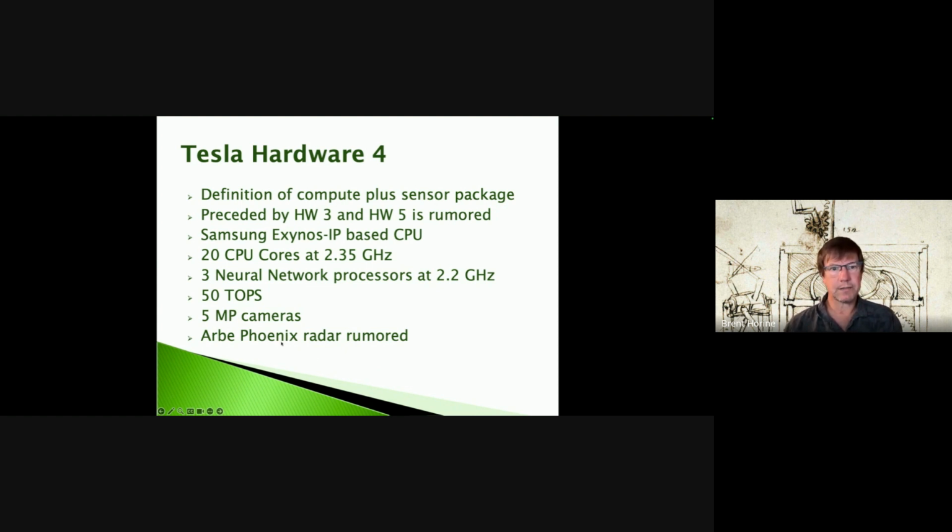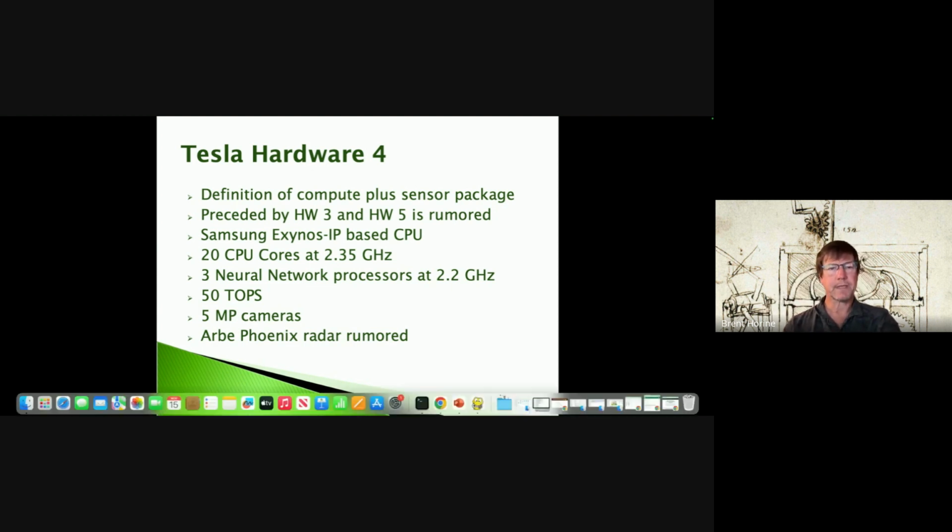When we looked at the FMCW radar, we used TI as kind of our base case. You had a data sheet from TI in your home assignment, but Phoenix is another major player. They're doing all the tricks we talked about. When you go to MIMO type processing, where you have multiple transmitter antennas and multiple receive antennas, you can get closer to an imaging type of radar.